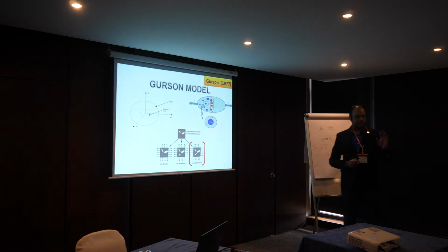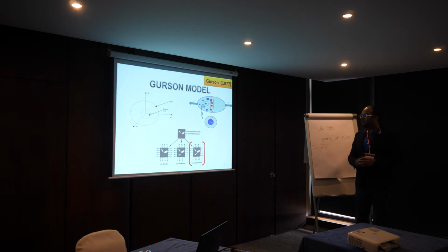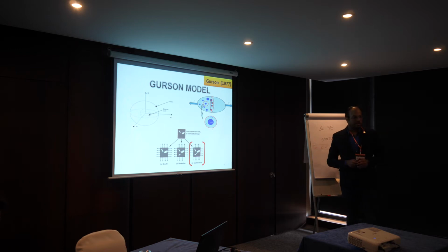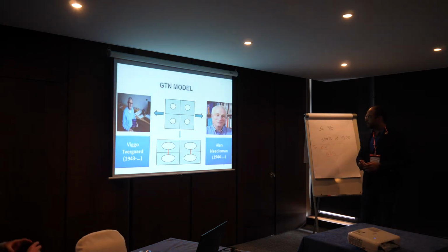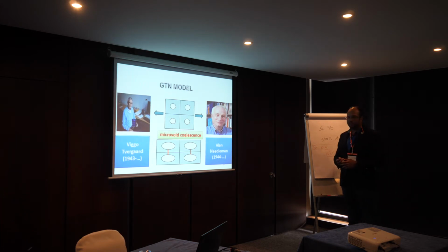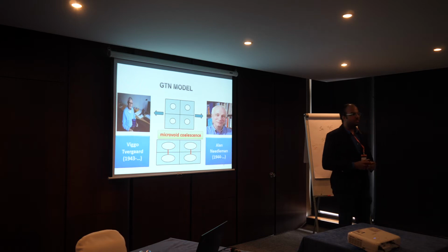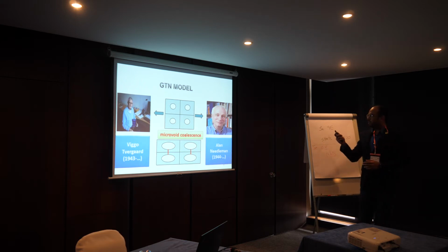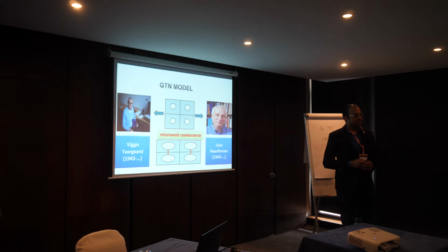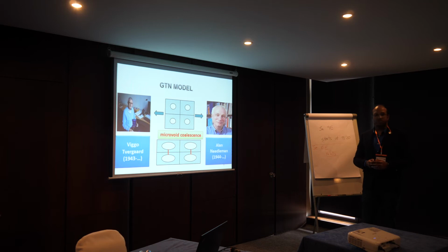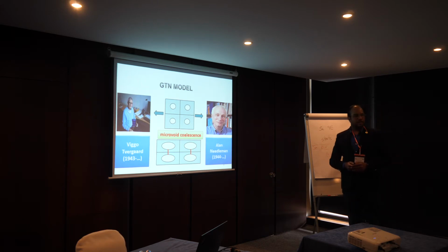As you know, we have 3 steps of ductile failure. Basically, in 1975, Mr. Gurson developed the model, but he didn't take into consideration the last step of ductile failure, the micro-void coalescence. So in 1986, Mr. Tvergaard and Mr. Needleman could include the micro-void coalescence in the model, which means that the GTN model could cover the 3 steps of ductile failure. And they developed the GTN model. As I told you, in the last 10 years, Mr. Zhang developed the complete GTN model by introducing other parameters. So I'm not going to use the complete model; I'm just going to base my work on the GTN model that was developed in 1986.